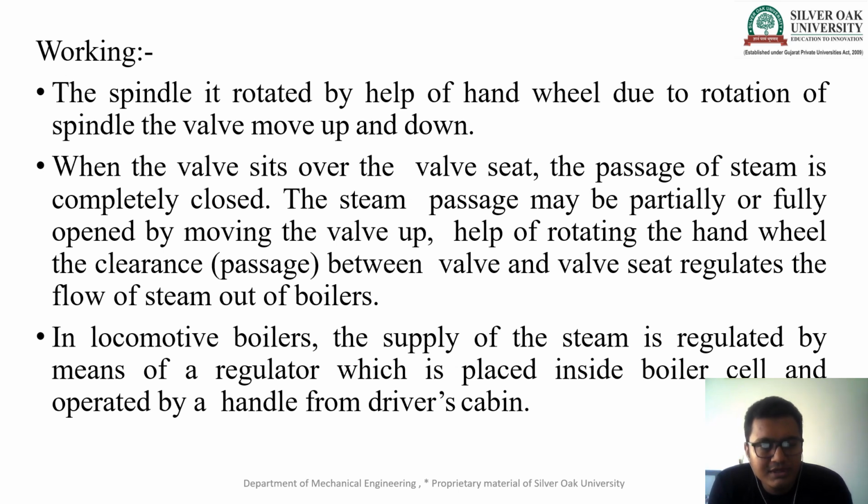When the valve sits over the valve seat, the passage of the steam is completely closed. The steam passage may be partially or fully opened by the movement of the valve with the help of rotating the hand wheel. The clearance between the valve and valve seat regulates the flow of steam out of the boiler. If we require more steam, we have to open the valve more. If we require less steam, we have to open the valve less.